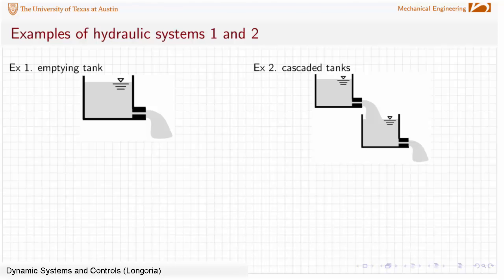But it gives us an opportunity to again review some of the basic ideas behind the model elements that we'll use. Now, when you're looking at this system as compared, for example, to an electrical system where it's really clear, here you do have to make some kind of decisions. When we call something a tank, right? We're usually saying that we're making an assumption about it being sort of a vessel that can hold water as opposed to a pipe.